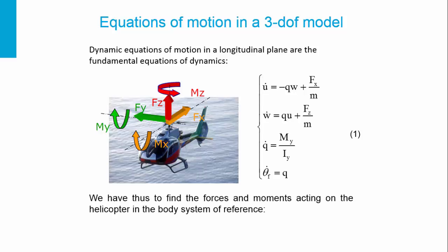You first have to recall the fundamental equations of dynamics. The longitudinal motion is of course involving the horizontal velocity u, the vertical velocity w, and the pitch rate q. And this is the fuselage pitch. These are the fundamental equations of dynamics that you have learned in the third year. Therefore, we now have to find the forces and moments which are acting on the helicopter in a body